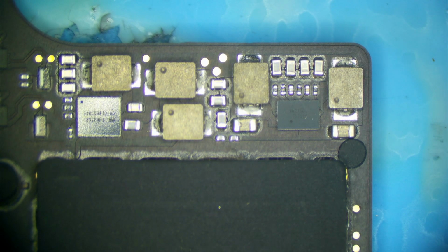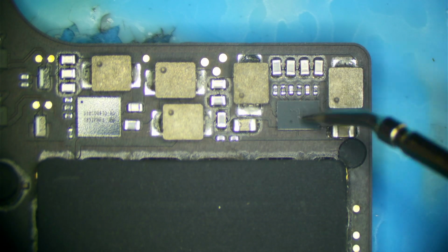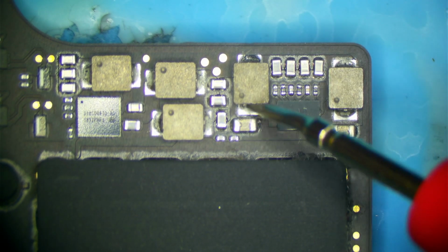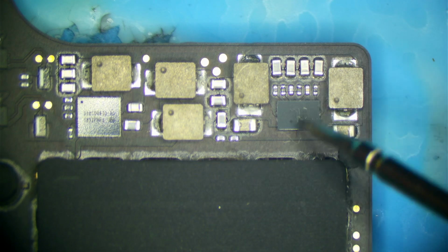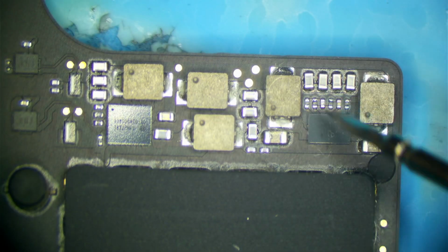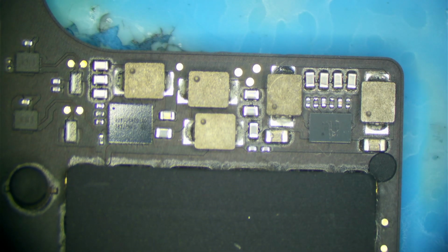So this is the chip in question right here. Alright, these really commonly get corroded just from dust in the air, and those usually lead to this chip shorting its input voltage to its output, which is very, very bad, and that kills our NANDs. This area is unremarkable, but it is a good sign that I have 2.5 volts here.